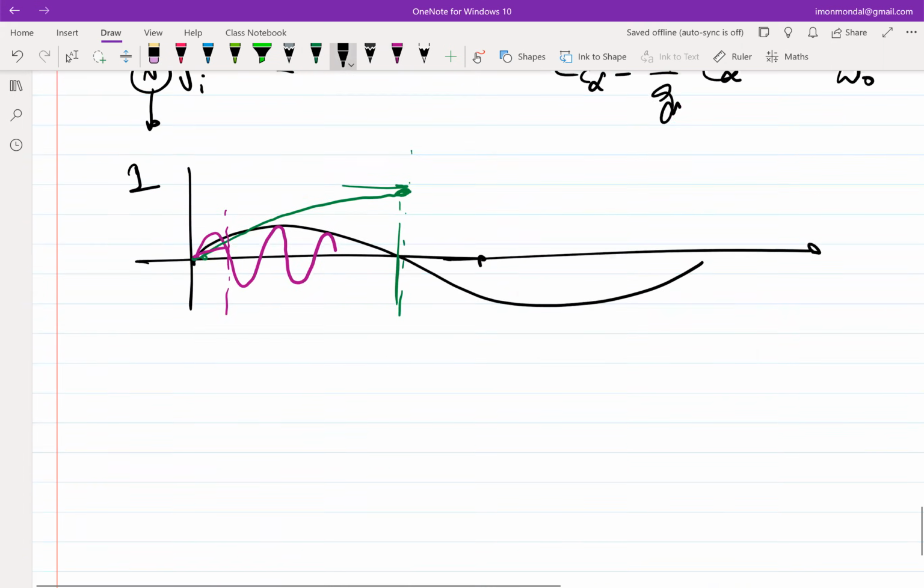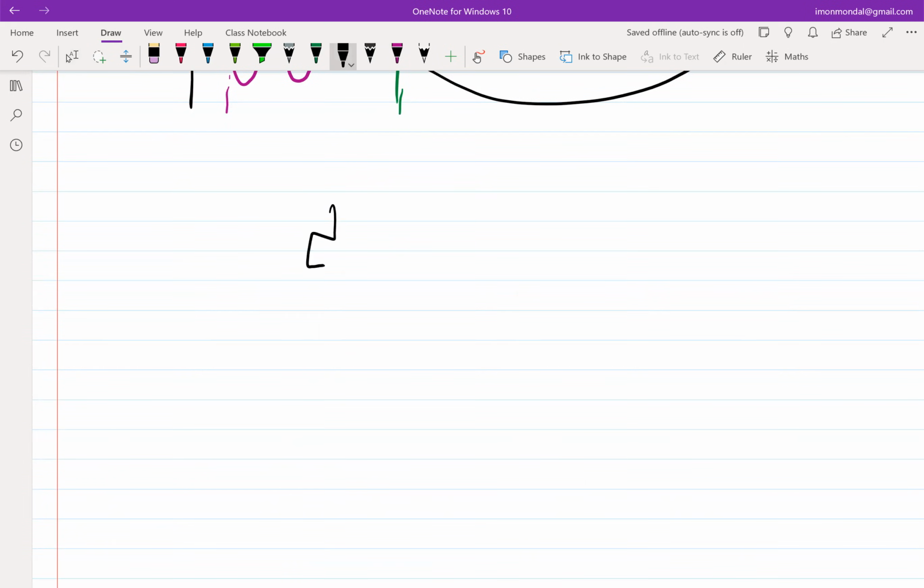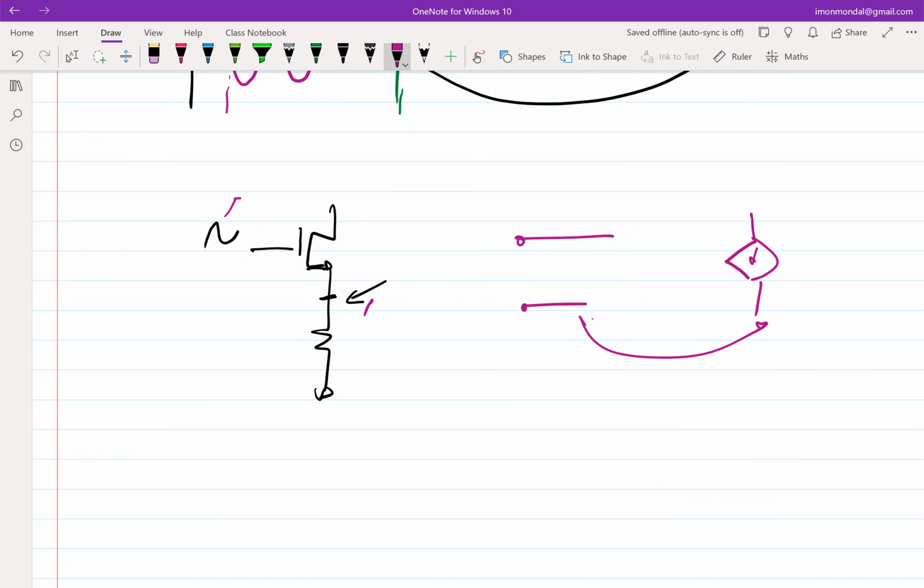Yeah, I think I get what you are saying. What he is essentially trying to say is that if I apply the voltage here and find out the voltage here, it's GMR by 1 plus GMR, right? Exactly. But when you apply it here and observe here, you are not breaking the loop, because the loop is connected internally through this. So in order to break the loop during analysis, you'll have to assume this to be a 4-terminal device. Good question.